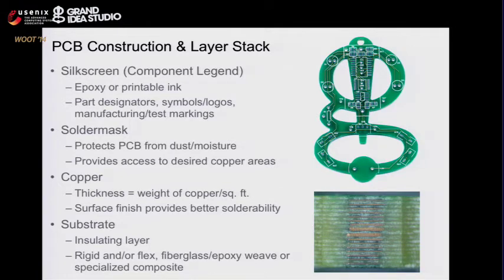So PC board construction, in a nutshell, is basically layers of materials, whether they're conductive or insulating, and creates this sandwich of material. You also have on top what's called a solder mask, which is basically a coating, in this case green, but it can come in lots of different colors, that prevents and protects any copper from being exposed that isn't intended to be exposed. So for the top and bottom layers, you're usually going to have a solder mask coating on there that we're going to need to get through to deal with those two layers. And then we'll want to get through the substrate to the other copper layers underneath. You also have a silk screen layer on top that gives you interesting engineering information that could be used for all sorts of other hacking stuff.